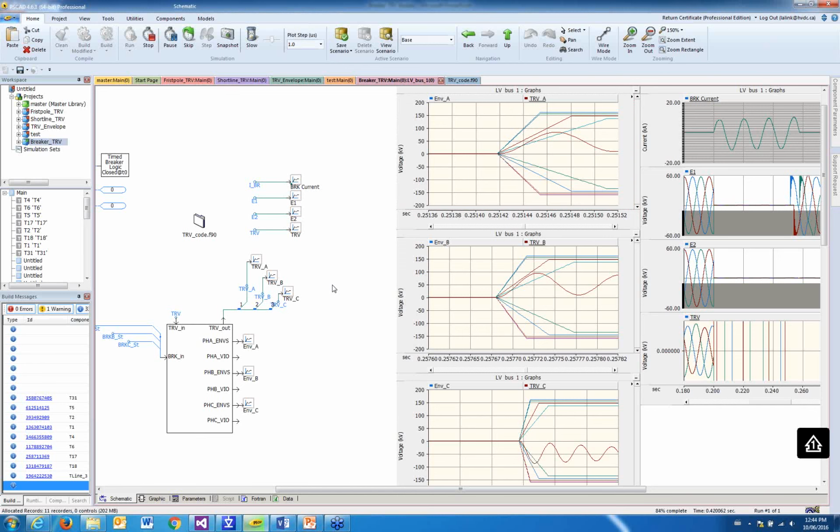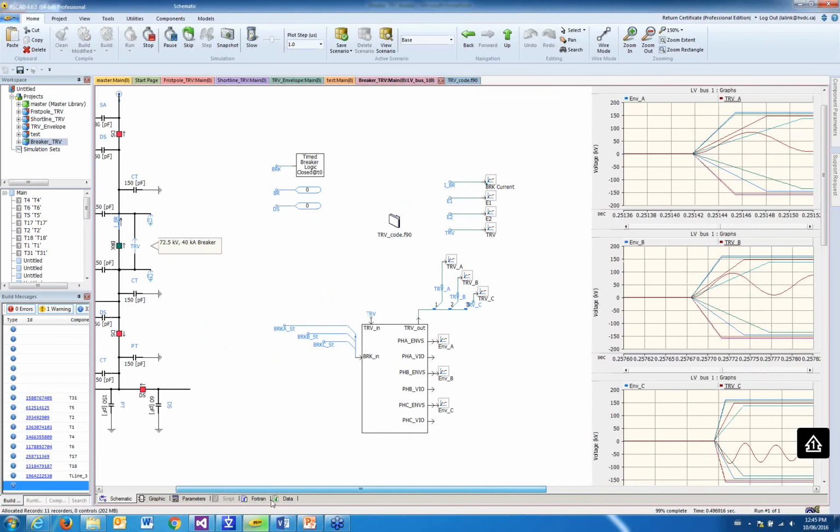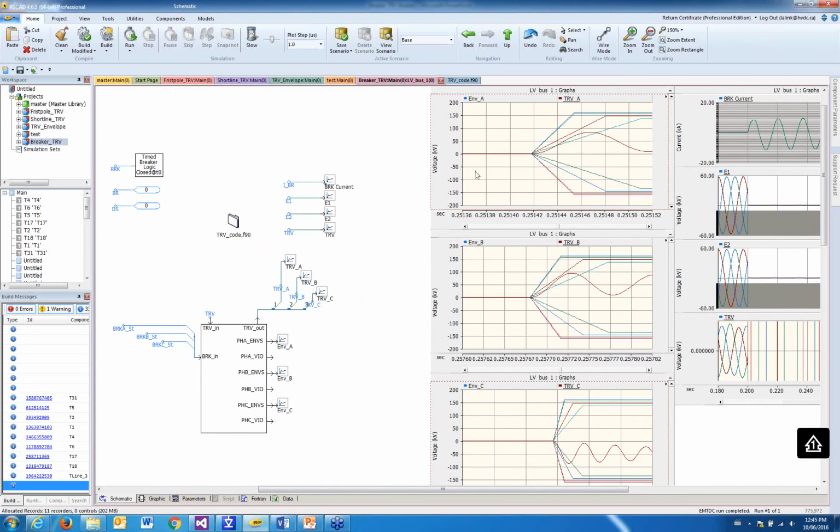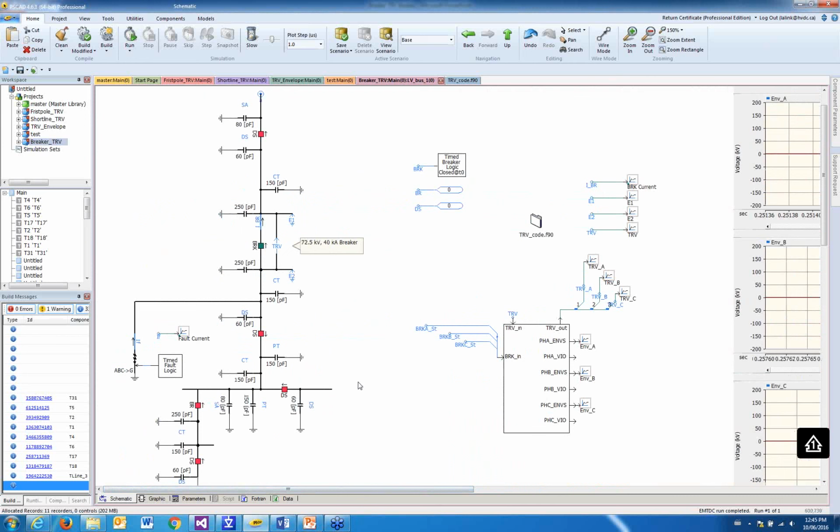For example, if your breaker breaking capability is 40 kiloamperes, then 60% means 24 kiloamperes. You can interrupt more than 24 kiloamperes of fault current without any problem in this situation. If it is something like 10-15 kiloamperes, you won't have any issue. So I think we're done with this simple demonstration on the terminal fault.